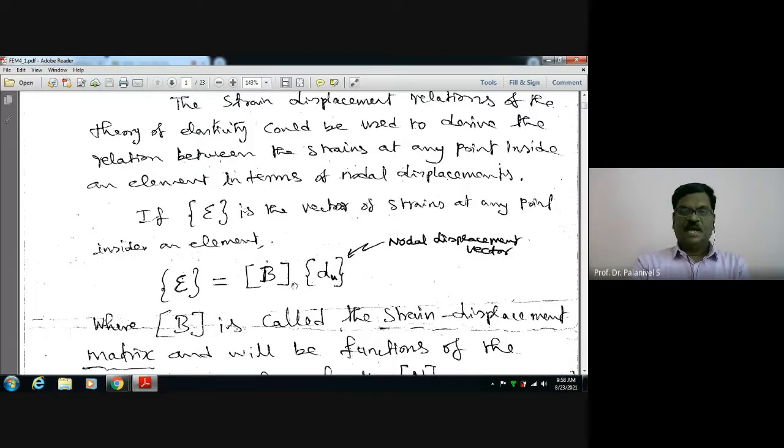Okay, already you have the u vector, that is the variational displacement, otherwise the displacement vector, equal to N, the shape function, into the nodal degrees of freedom. That relationship, you know how to develop shape functions for various elements. We have seen it in detail. Okay, now we are going to see how to obtain the strain within the element. So there is a matrix that relates them. How do we obtain it?